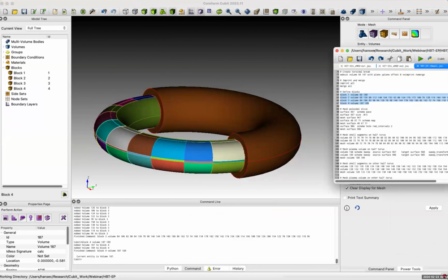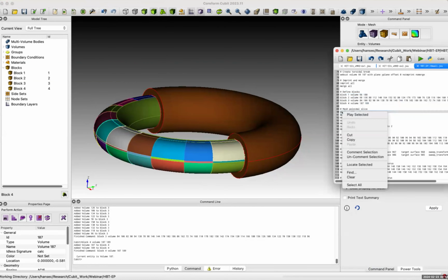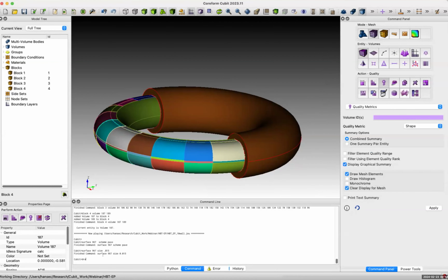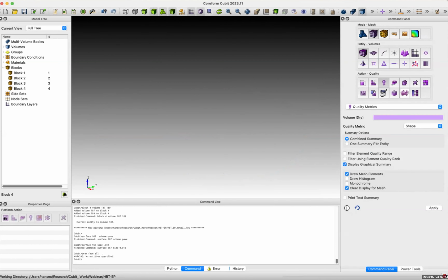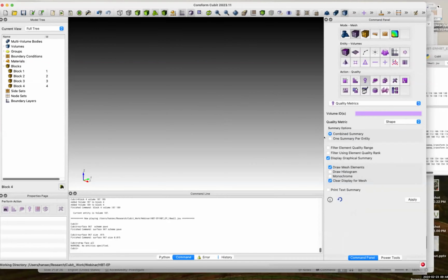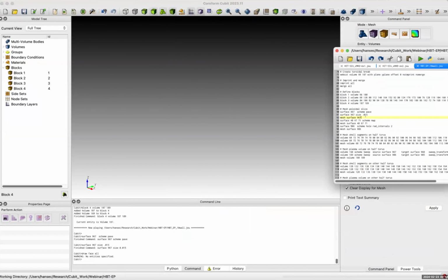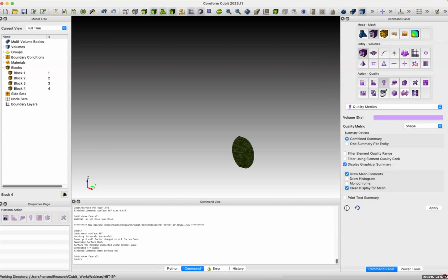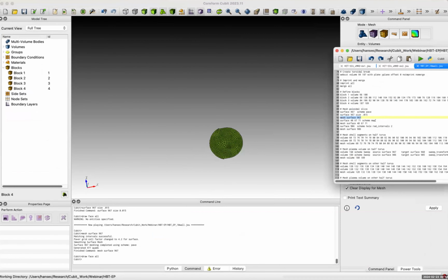Okay, so now I'm going to start making the mesh on the surface. I'm going to start out by making the mesh on the plasma. And then I just want to look at the mesh. So I'm just going to go here and say draw face all. Maybe I didn't actually make the mesh yet. Oh, yeah, I didn't make the mesh. All right, so now I draw face all. All right, and so now we can see this cross section that I'm building up. So this is the mesh in the plasma. In this case, I'm just using a pave for simplicity.